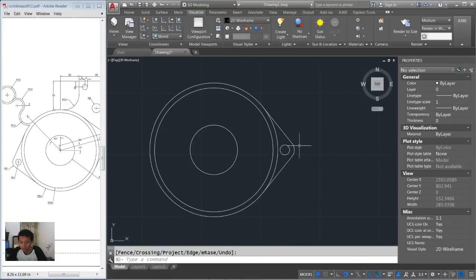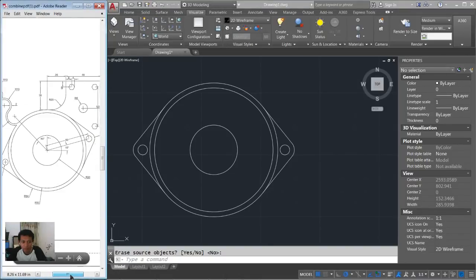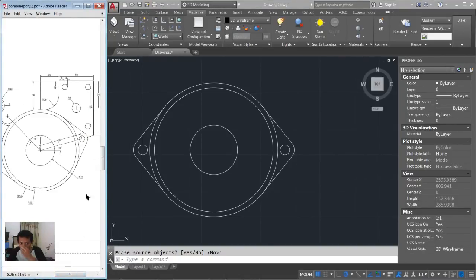and then you can use the mirror command to mirror this object, starting from this point to the top here. We use the rotate command to rotate this object with an angle of 15 degrees.